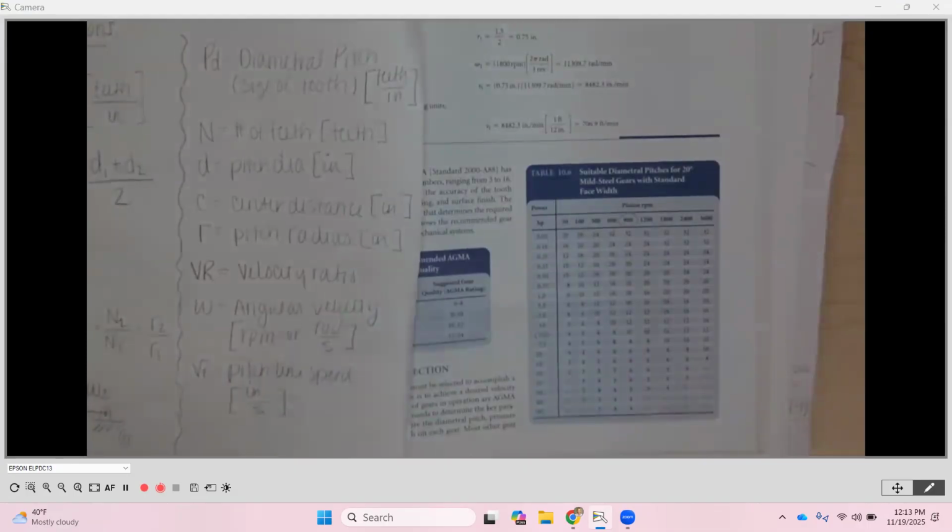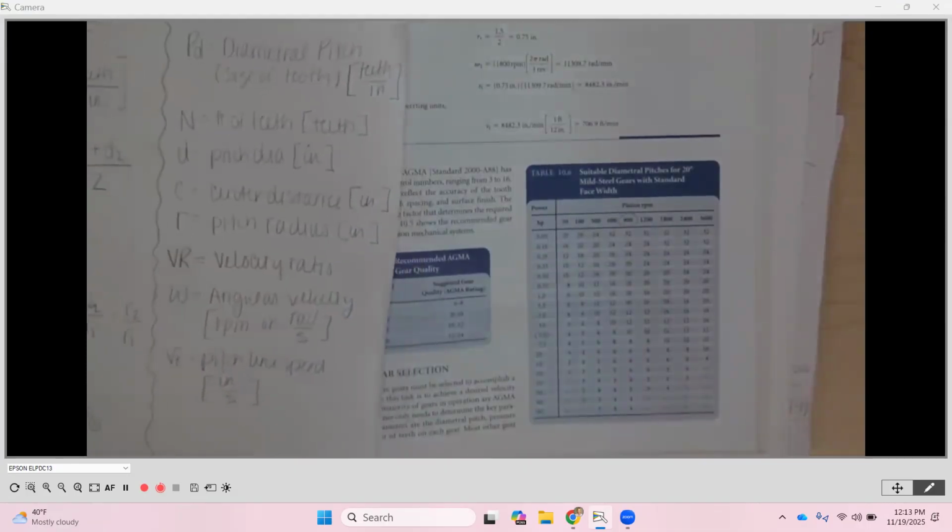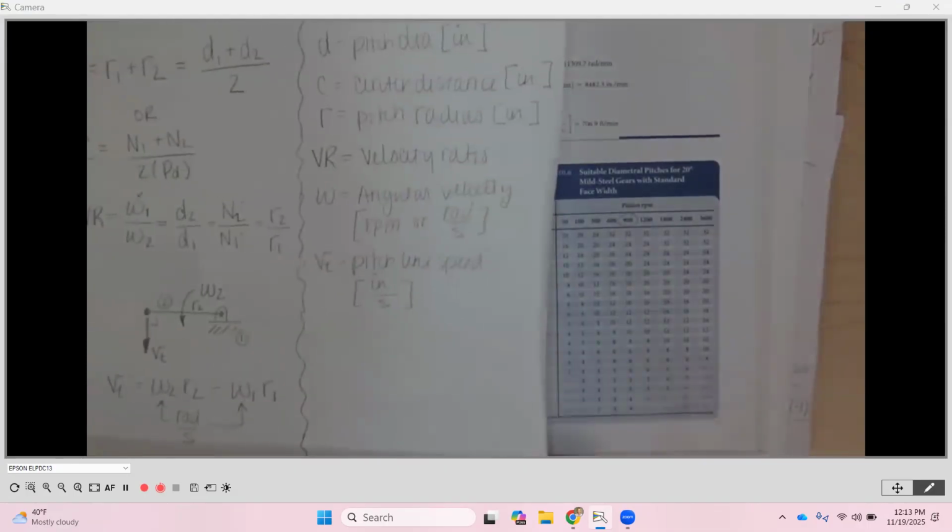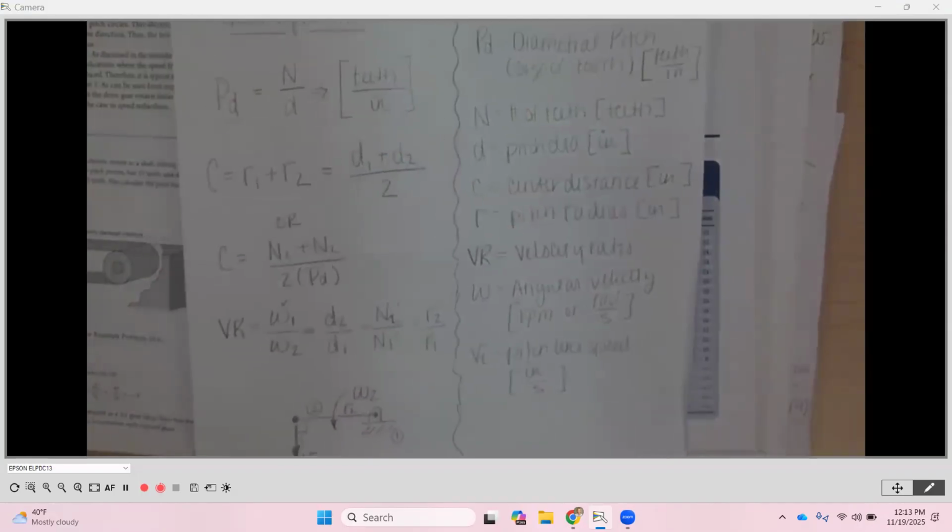So over on the right-hand side was just the definitions and the units and so on that we would be expecting. Like I said, kinematics is all about those first phases of the design process that I need before I'm worrying about forces. Notice we're not worried about how much force is here, or what the stresses on it are, anything like that. We're just looking right now at layout and how fast things are going.